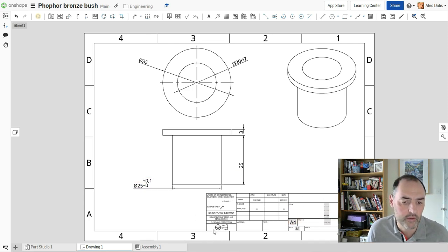Okay, the rest of the drawing I'll keep quite short, so I won't go into all of this, but we need to add a title, a drawing number, material, and tolerances here. The general tolerance shown on your sketch is plus or minus 0.25. So it's only these two dimensions that need a tight, specific tolerance on the drawing. Others will all be plus or minus 0.25, and that's shown in the tolerance box here.